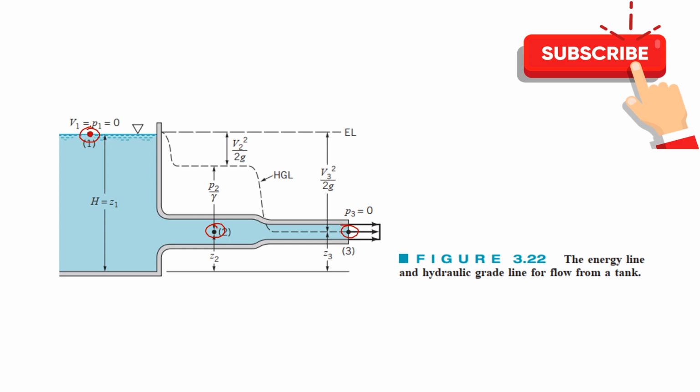the total head is equal to the elevation head, because at point 1 the velocity of the fluid is 0 and the pressure is atmospheric, so the pressure will also be 0. So overall the energy line, if we want to represent it right now at point 1, will be equal to Z1, that is equal to the total elevation head. So this is for point 1. Now let's move on to point 2. This is our point 2.